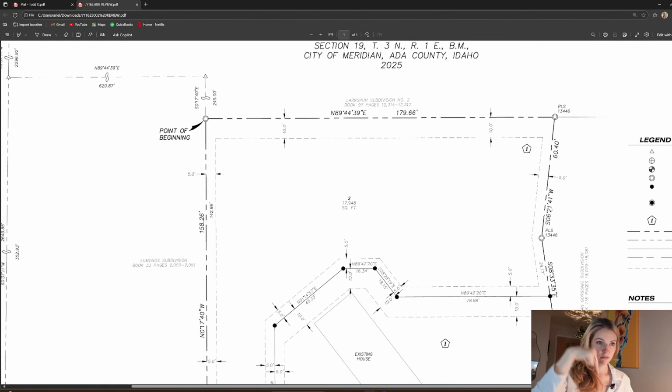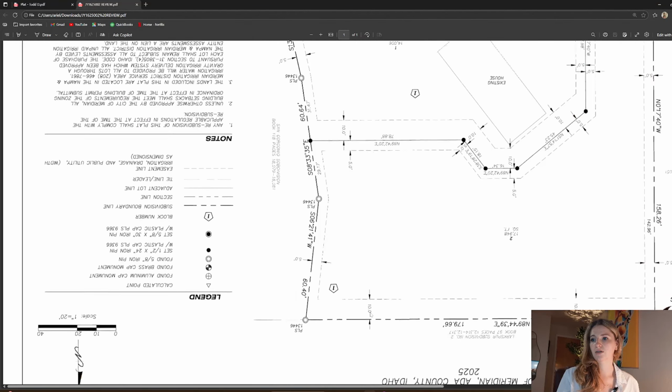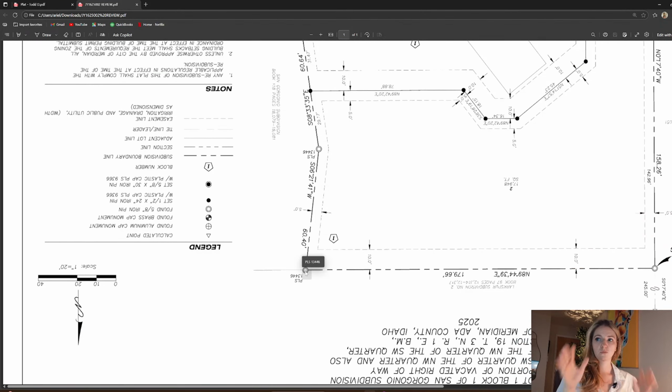Now we're standing there staring straight south. So it sometimes can make sense to orient yourself this way. Now we're standing here, we're staring straight south, and we're going to turn 6 degrees, 21 minutes, 41 seconds. This is how I've had it explained to me, as minutes and seconds. So some people may say it differently, but you're going to turn just to your right that much, and again you're going to walk 60.40 feet.